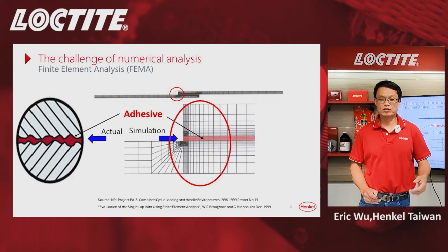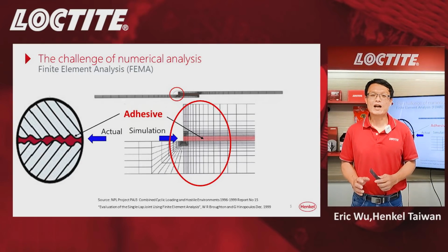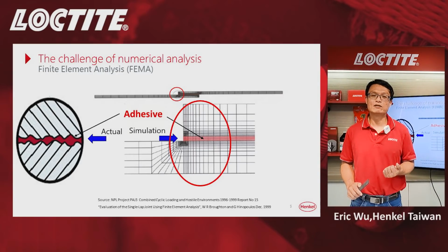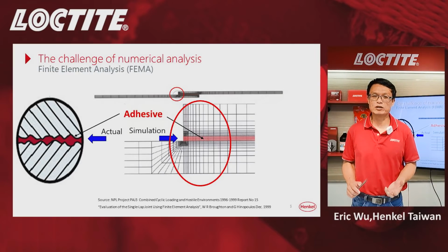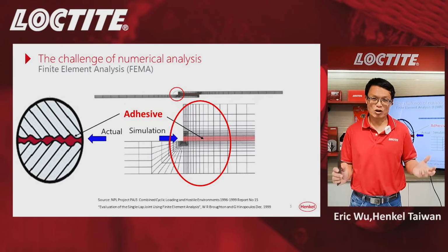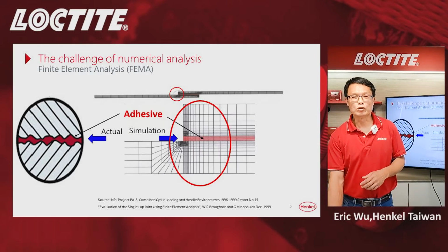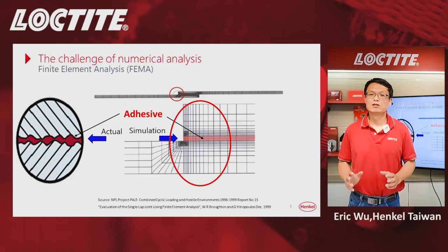So coming to this point, we understand that for composite material bonding, or I can even say for most adhesive bonding, you can't do the analysis by mathematical model. And also you can't use a very simple static test to simulate the structural strength when dynamic loading is applied to the overall structure. So these two big challenges lead to a direction for all design engineers. We need a test. We need a test to collect data which is meaningful to our design.